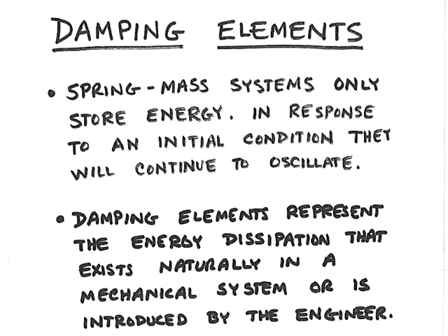Damping occurs naturally in all mechanical systems due to the energy that's lost in terms of heat with any sort of internal motion within a system. After all, systems with only elasticity and inertia would not lose any energy. Elasticity stores energy as potential energy, and inertia stores energy as kinetic energy. And so a system consisting only of spring and mass elements would continue to oscillate forever.